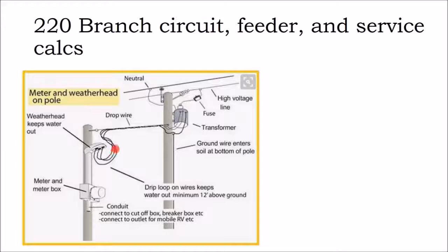Now, I've seen situations where the utility has come out during an install and installed the transformer and these power lines ahead of our commissioning, and they taped up the wires that were hot, and I've seen these wires sway in the wind and touch the side of a metal building and cause a ground fault that blew apart some connectors on my grounded solar array.